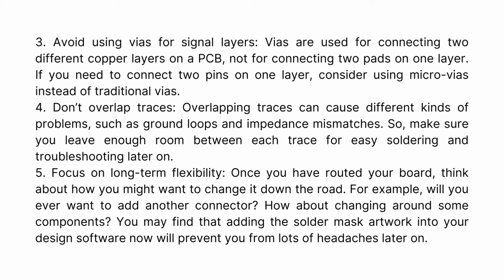4. Don't overlap traces. Overlapping traces can cause different kinds of problems, such as ground loops and impedance mismatches. So, make sure you leave enough room between each trace for easy soldering and troubleshooting later on.